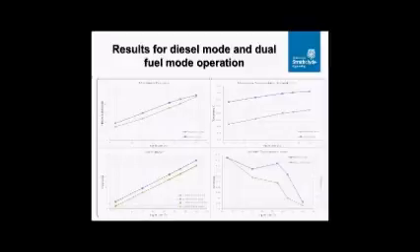In the dual-fuel mode, the engine operates at lower receiver and in-cylinder pressure levels. However, the mean effective pressure and power output are kept at the diesel mode levels.